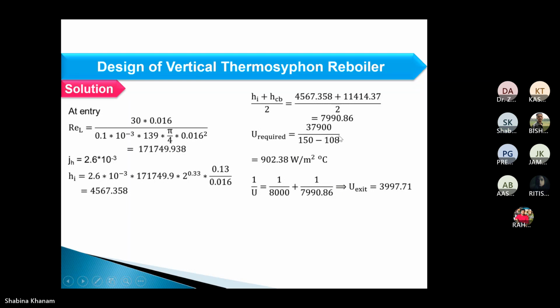Okay, and heat flux over here again, at which the recirculation ratio will be maintained. Okay, because we have not done iterations over here, so we are considering the same thing, same flux, but you need to reiterate that. Okay, so actual Q will be counted over here, divided by this delta T mean, and that is because isothermal condition in both ways, so that you can consider as it is the difference of these two.